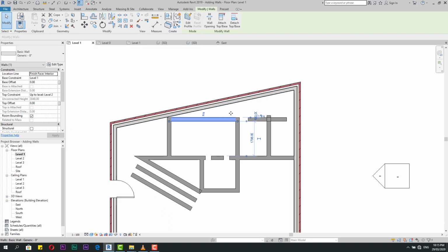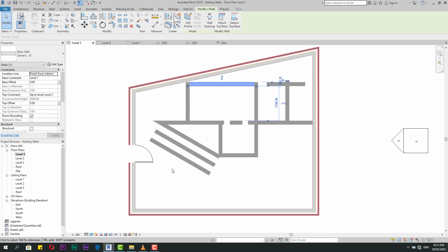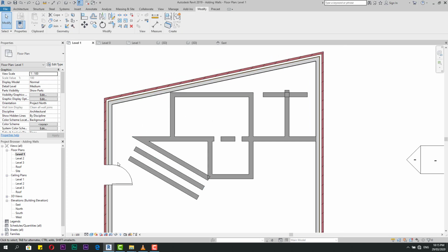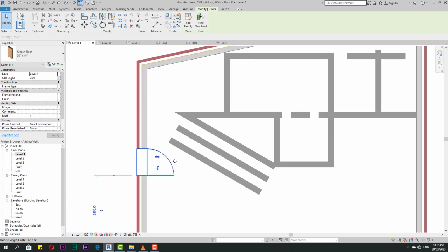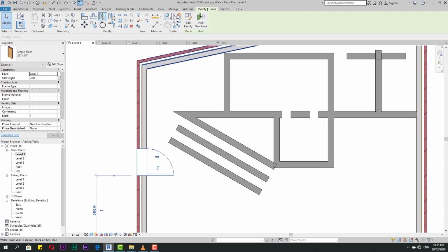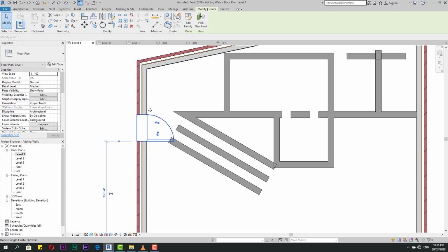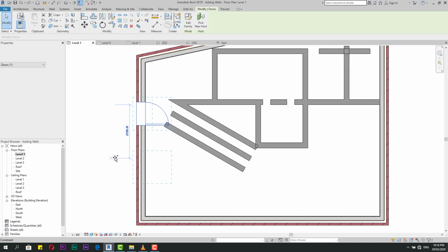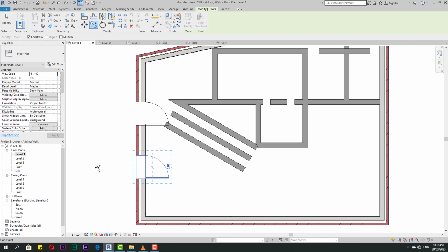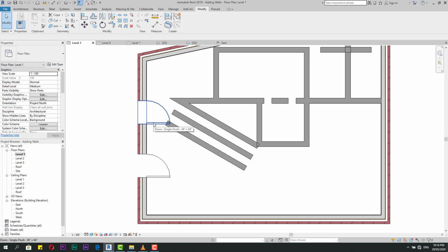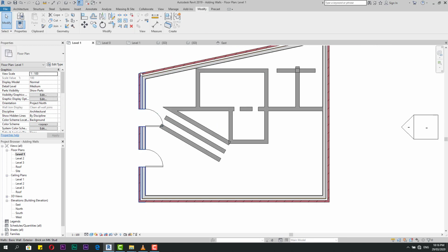From this, you can make delete or you can delete from keyboard. Now we speak about walls. But take care, when I select any element like door, say most of them it's active and you can move or copy. But when you make copy, you must copy it in a wall. But if you need copy out here, you can't make door without wall. He is smart and understands this.